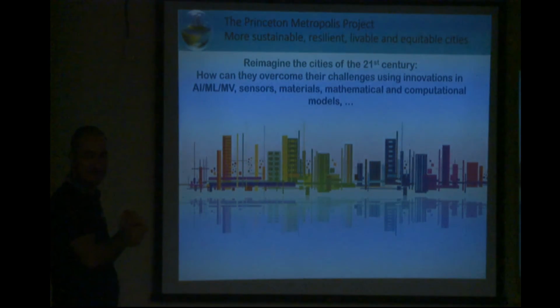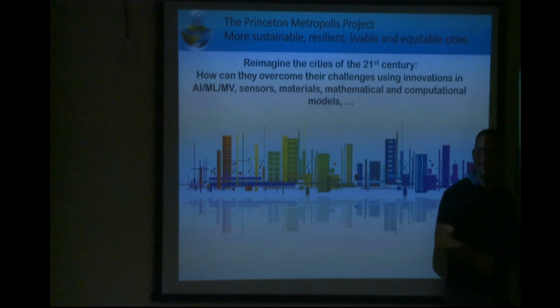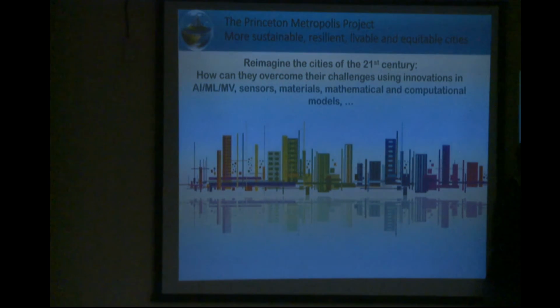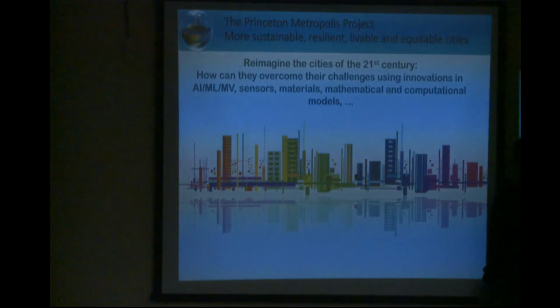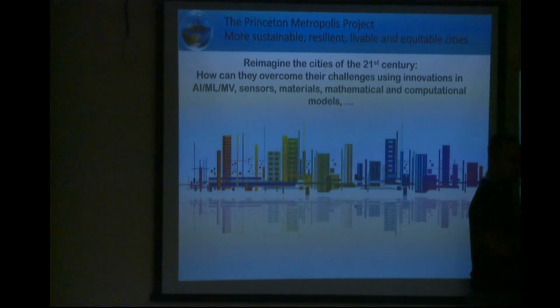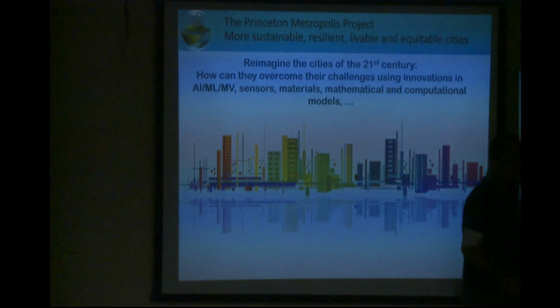Any more questions? Then the heat fluxes are more complex, because you need to add a term for heat here. Heat, the way you do it is that when you're doing the IBM, you add all these forces. But then what happens at the boundaries? So you create a layer of ghost cells or extra cells, and so you create an extra mesh around the building.